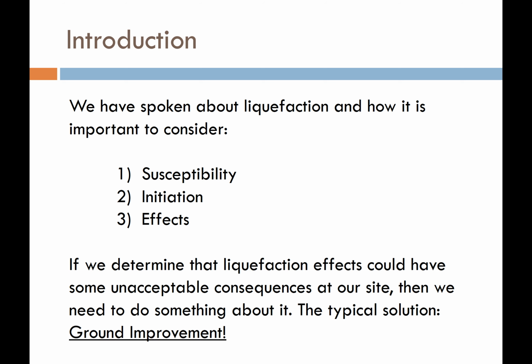One thing we can do is just increase the stiffness or the strength of our structure to resist the loads and deformations that we anticipate will be applied due to the liquefied soil. That's one thing that we can do. Stiffness of structure. The other thing, though, that we can do, and that is commonly done, is just improve the quality of the soil itself.